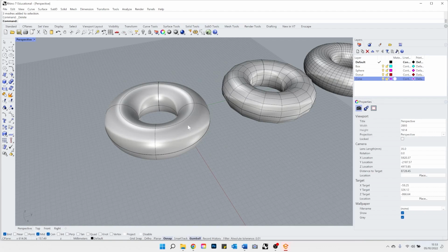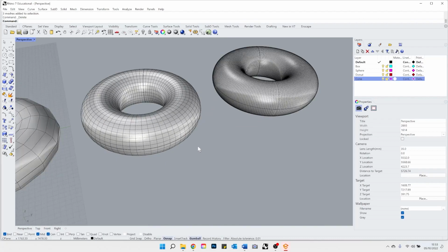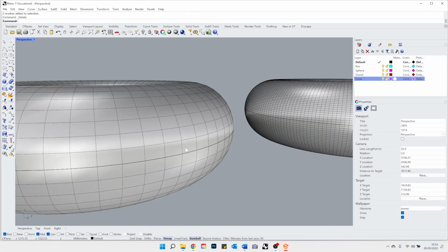But if you start to have a really large model with a lot of elements, and you start to union those elements into one single shape, this is when your file starts to get really heavy. So imagine if you had two cubes and you unioned them into one single object, straight away you have a complex object with a lot of splines. So the computer every single time needs to think how to fill up the space between those splines. So your file is starting to get really heavy. Meshes in comparison are going to be lighter because it's all about the amount of polygons you have.